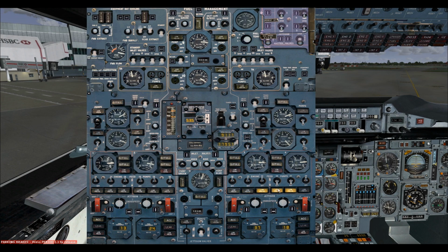They all need to be on. And then the last thing we need to do is turn on the D-air for, well, actually it's not the last thing we have to do. We have to turn on the pumps for tank 5 and tank 7. You need to turn on both pumps because the left-hand pump feeds engine 1. The right-hand pump feeds engine 2. Same with tank 7. The left-hand pump feeds engine 3, the right-hand engine 4. So you want to put both of those on.